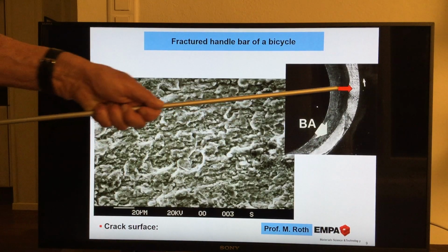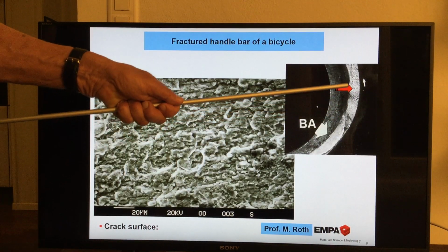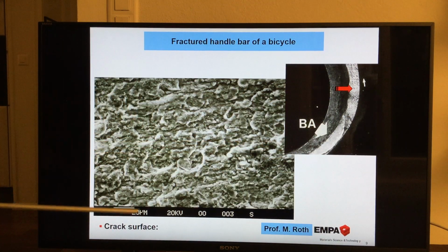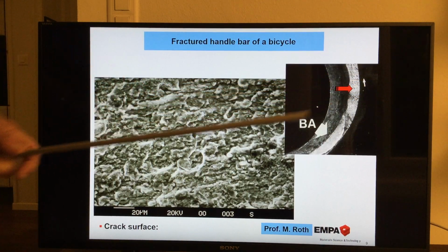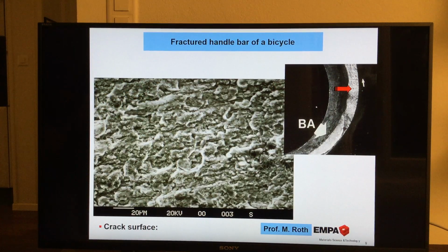Okay, now we go on this fracture surface. And we see here, in this area, when the crack propagates, now in the scanning electron microscope, see again here the scale at higher magnification. We are watching carefully here on the fracture surface, and now when you watch very carefully, you may see some parallel lines in this fracture surface.